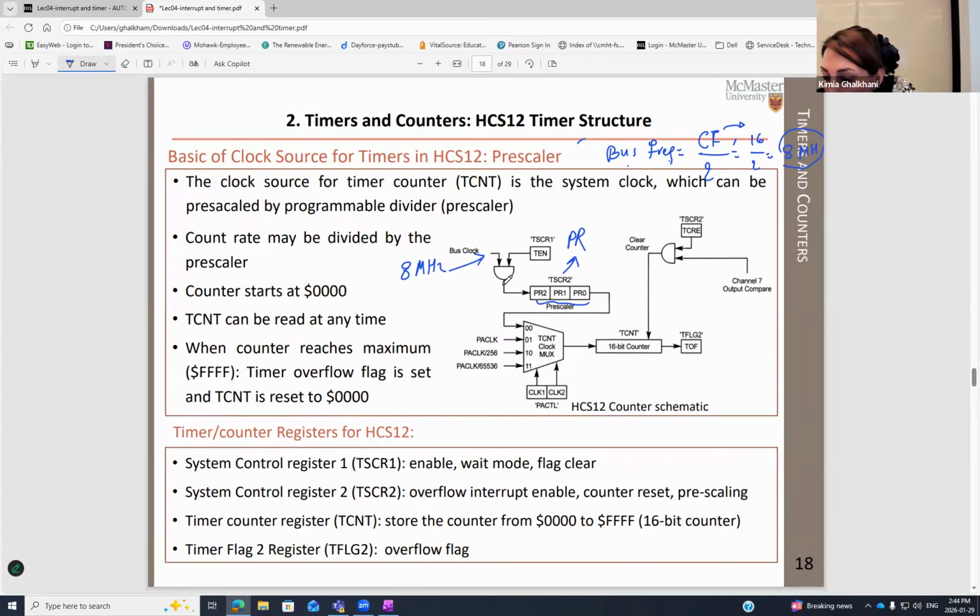It means we are going to have the control register, where only 3 bits of them are used in order to look at the frequency. This one will capture the frequency. It will send the command to TCNT right in here. And then in here, for example, if your bus is 8 megahertz, I'm going to have F to be 8. I'm going to calculate it. And then T, I can calculate from this. If I have 8, then I can calculate the T.